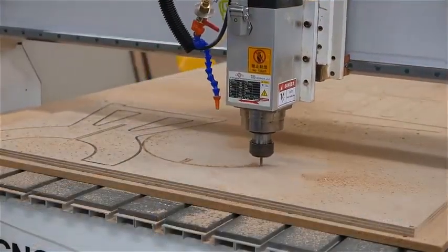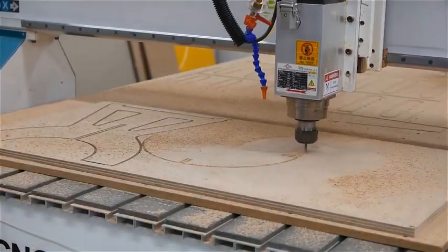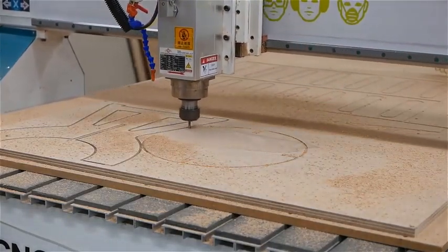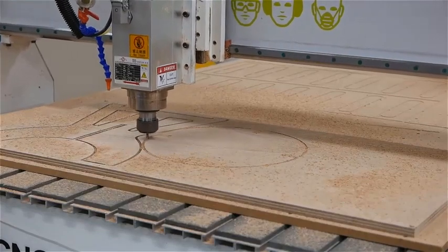Remember that 3 layers or 3 passes are machined to reach the full depth. The third layer creates the support tabs.